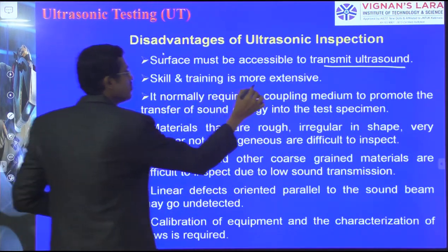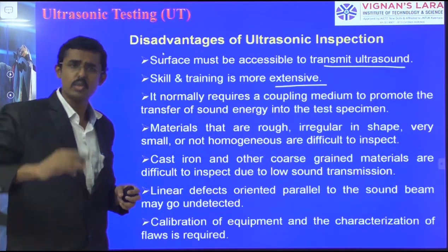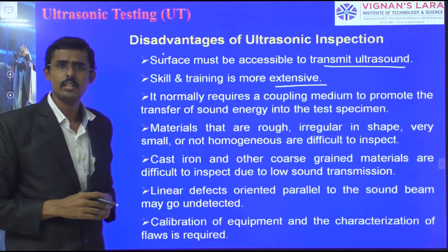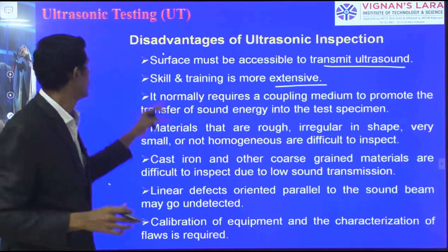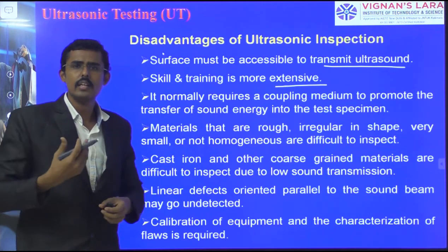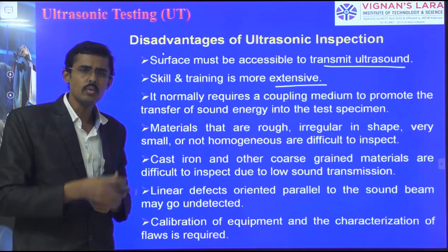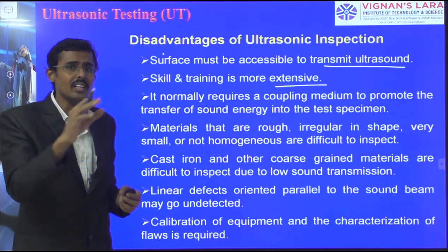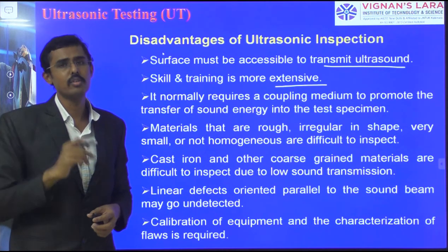Skill and training is more extensive, because in radiography also training is required to set up and to protect, safety purposes are required. Here also it is required, because if the operator does not know what this echo represents, then obviously we can't find the defect.